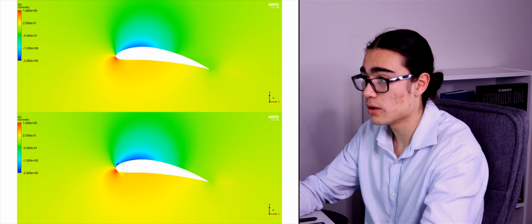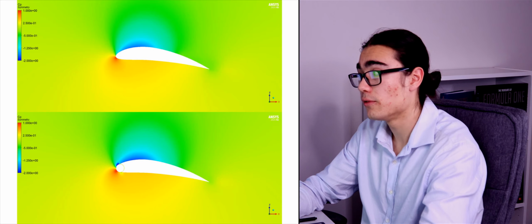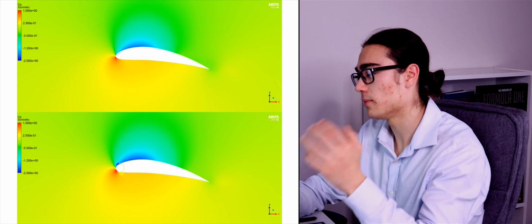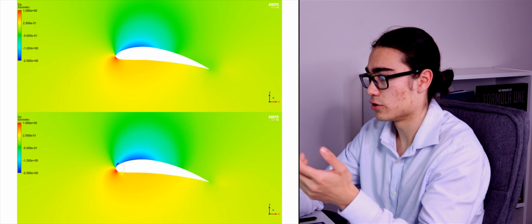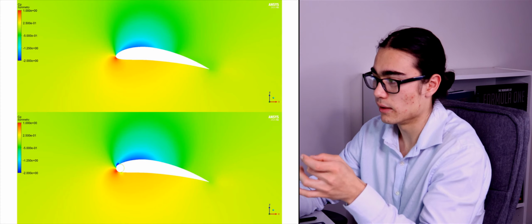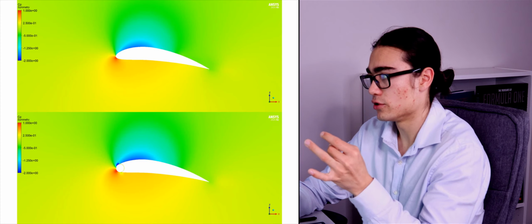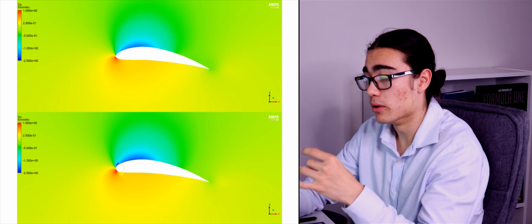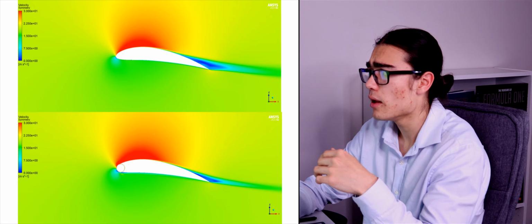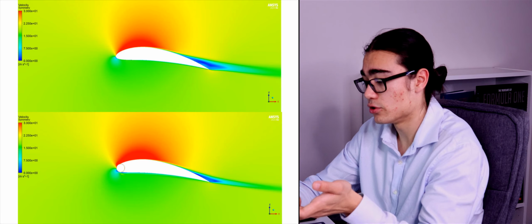This is just a coefficient of pressure, and in general we were very successful. So we had 7% more lift and 19% less drag. You can clearly see the biggest differentiator there is on the top surface. We've gotten a lower coefficient of pressure pretty much all the way over, and we've got that spike where the actual cylinder is rotating, which is what we'd expect. You can also generally see a higher coefficient of pressure underneath the airfoil, but ever so slightly, especially related to that top side. I've also got a velocity plot here, which is confirming our suspicions that we've decreased separation.